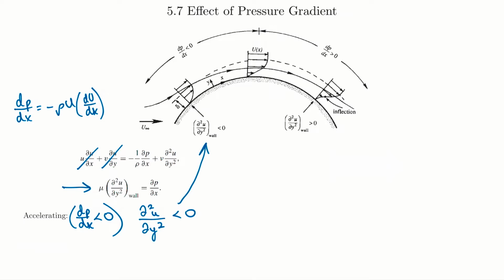Now the velocity profile, we know, has to blend in smoothly with the external profile at the edge of the boundary. So the slope, du/dy, just below the edge of the boundary layer decreases with y from a positive value to 0. I'll show that specifically. It goes from being a positive value to being 0. That's how much u changes in the y direction.